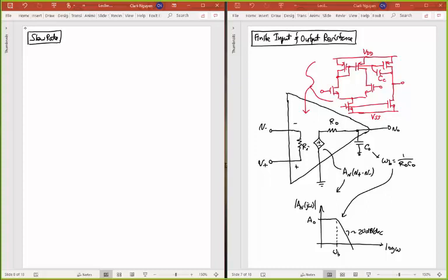To do this, let me just take an example. Let me take a unity gain follower circuit that uses an op-amp. And if you don't know what this is, I'm going to draw it for you. Hopefully you've seen this before. This is just an op-amp buffer. And so here's my op-amp, plus terminal, minus terminal. I'm coming in with an input right here. And all I'm going to do is tie my negative terminal to my output. And if I do this, I'm going to get basically a gain of 1 across this. That's why it's called unity gain. But it's a buffer because what it does is it makes my input resistance look enormous and my output resistance look very small while still keeping a gain of 1. And so there's a lot of reasons why I want something like that.